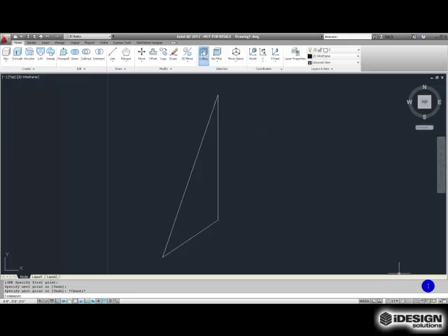Over here you also have some other settings for annotations. You have an annotation scale, turning annotation on and off. This will add the scale to specific sheet sizes. You can change your workspace settings over here as well. The lock will actually make all your positions of toolbars and palettes permanent, so you can't accidentally wipe out a toolbar by clicking on it accidentally.